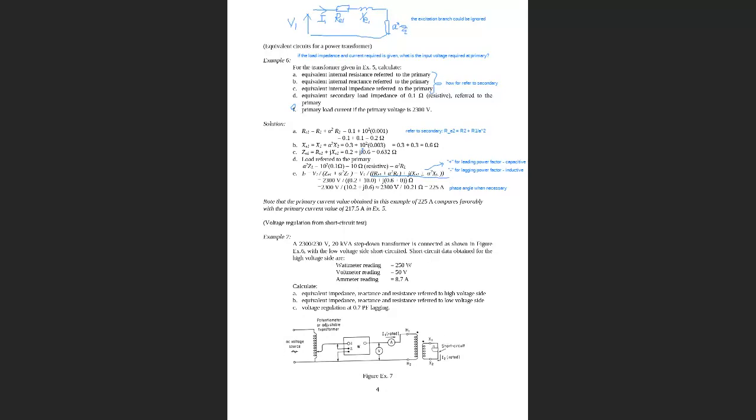So the low voltage side, with fewer turns, is short circuited. The high voltage side is applied with a small portion of the rating voltage. Here we are using a source transformer to get the necessary voltage to input to the high voltage side to get the rating currents. So we apply a certain voltage and get a rating current.